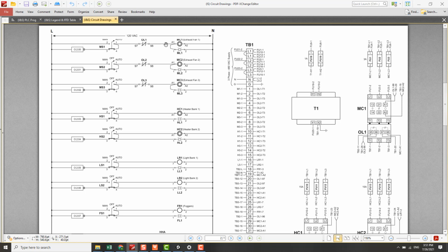One misconception when troubleshooting is that we always think, because this component did not energize, the problem must be from the PLC output circuit. Actually, this is wrong, because the problem is not necessarily from the PLC output circuit, even though the component that did not function is located in the PLC output circuit.